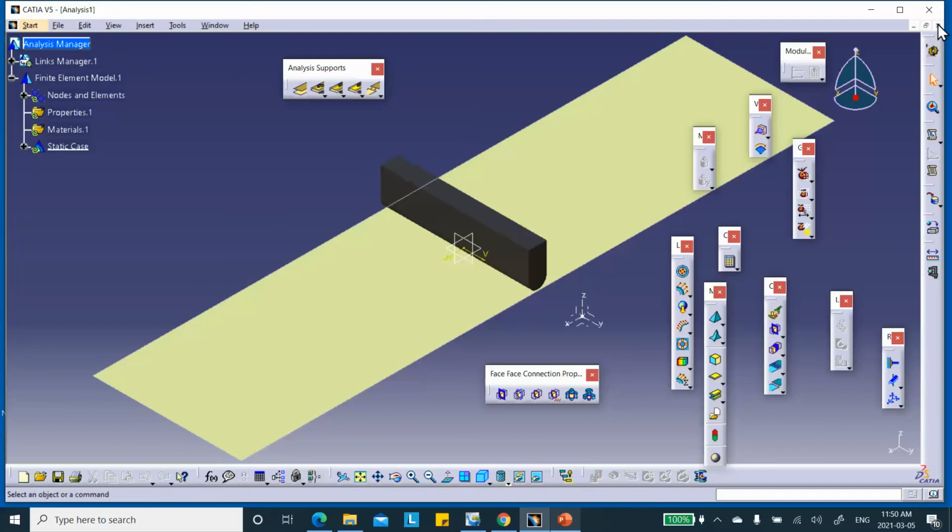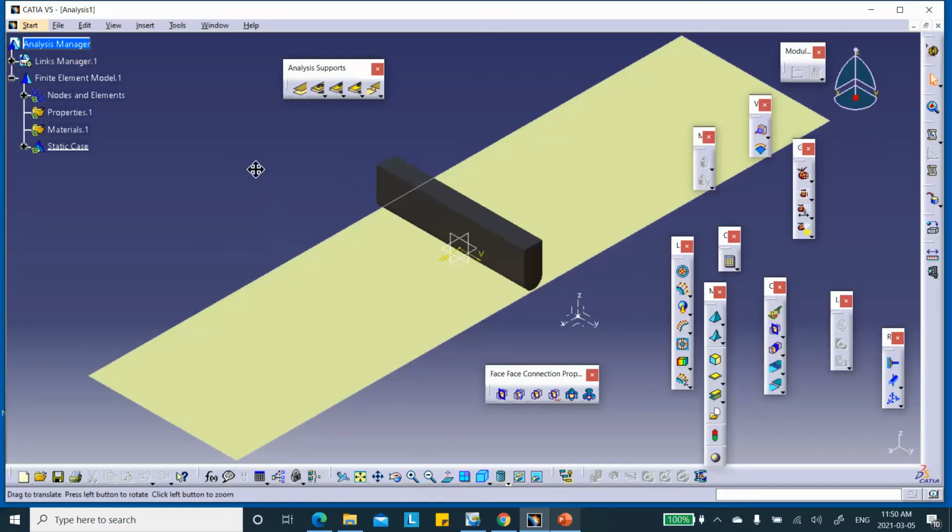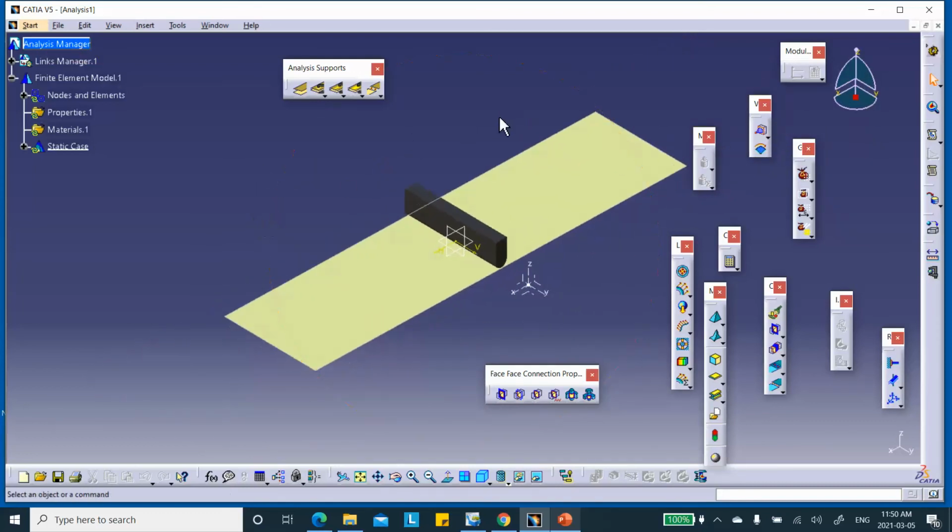Let me close. See, now I have to mesh it. When I measure it, it's solid element, it doesn't have 3D property, okay? So I have to go and create the 3D property. But if I had gone to the generative structure analysis first, it would have meshed this thing and I had one less step to do. So here's what I'm going to do. Unfortunately, okay, I didn't do that, so we'll stop.